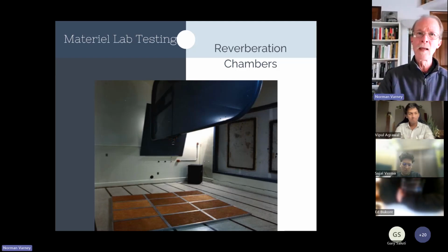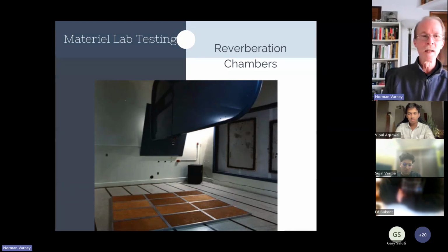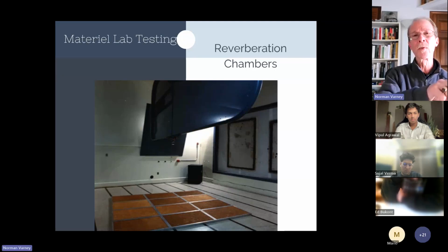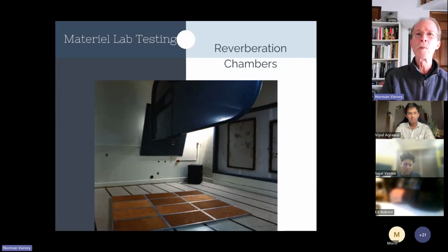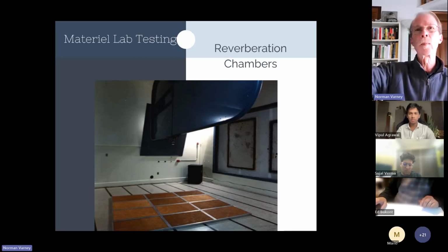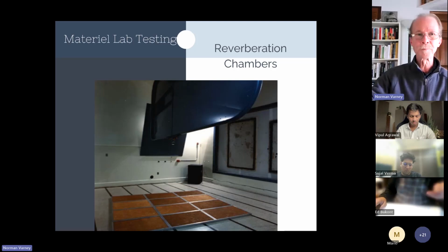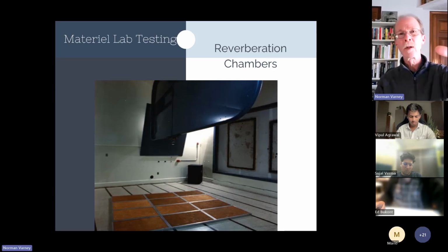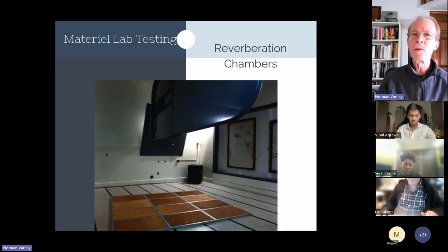You have to know how this material is performing, either from a sound transmission loss or a noise absorption standpoint. How is it performing across the different frequencies? That way, when you find that you've got quite a bit of reverberation in the mid range, what's a product that will address that? Or it's hanging down here in the low. Shoot, most of these products don't do that. You have to have the whole story.